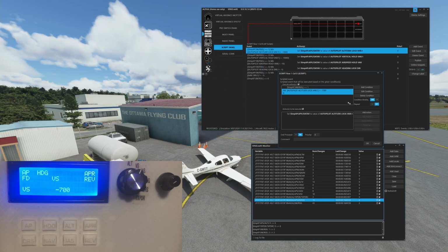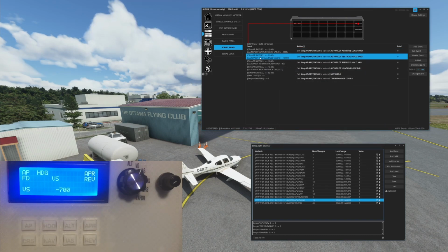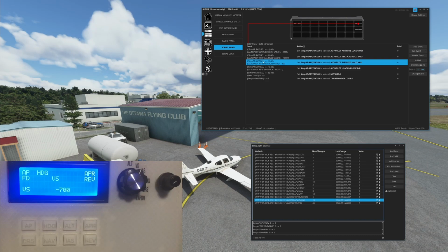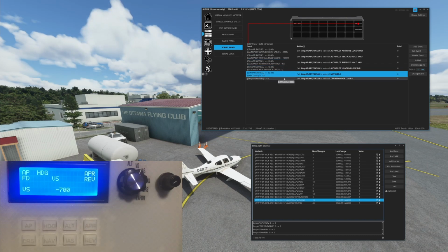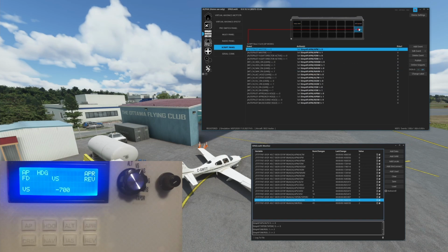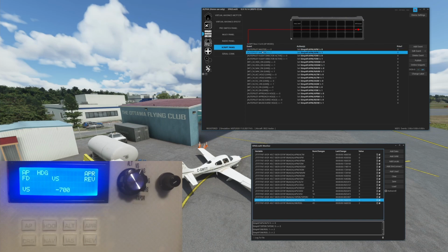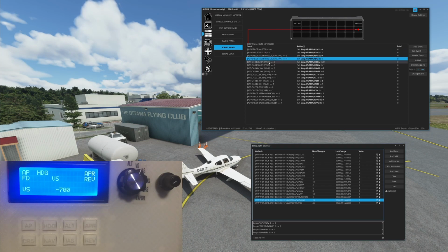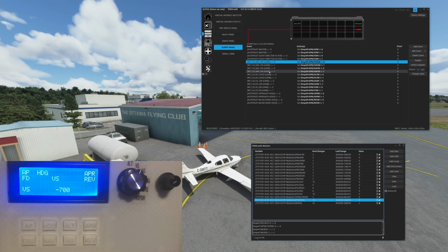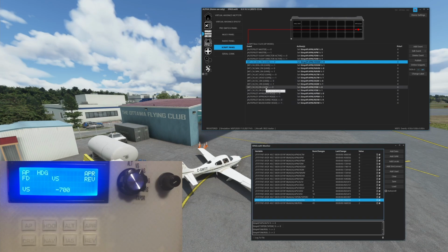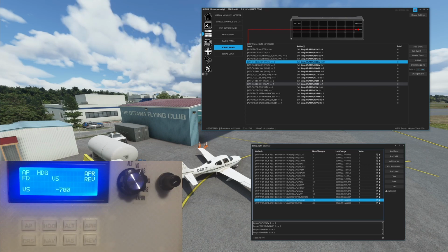So we just came in and we mapped those appropriately for our modes and our data. So we just did all those the same, worked perfect. And now for our autopilot modes, Autopilot master used the same variable, right? The flight director used the same variables, but all of the other modes, heading mode, nav mode, altitude hold, flight level change, VS, those were all using the new LVARs that the CJ4, the working title guys, added into the sim. So we had to change those out from regular VARs to LVARs.